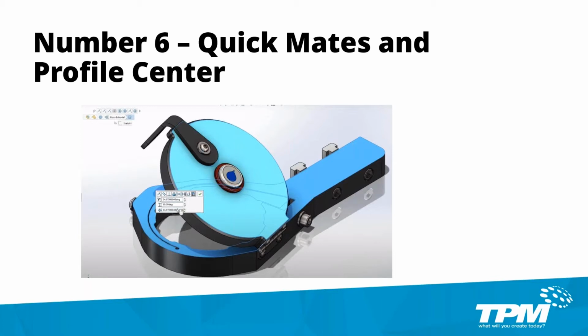So it's really easy for me to click on one of these parts, click the center plane, click on another part, use the D key again, grab that center plane, and use the Quick Mates toolbar in conjunction with all of those shortcuts to mate faster than ever.